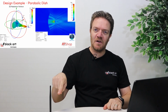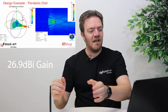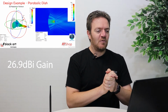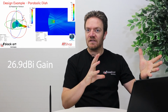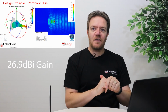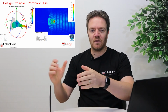So remember, I started off with a 2 dB little dipole. I made it a 6 dB Yagi antenna by just adding those components at the front and behind. I put it in front of a dish. This antenna now has 26 dB gain. Just by doing all those bits and pieces, adding a lot of metal around my antenna to come up with an antenna that looks like this. So that's how you take a very basic antenna, adding all the knowledgeable components around it to create an antenna.